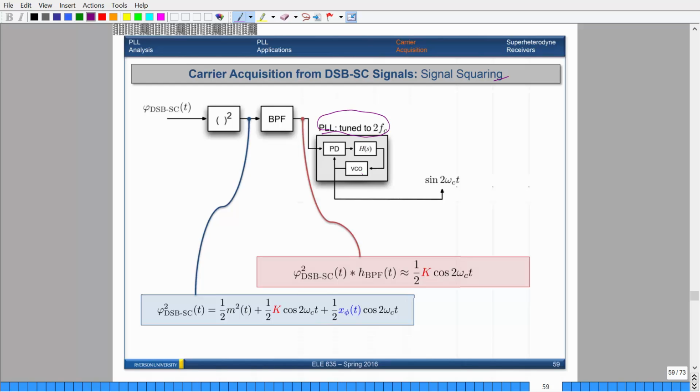So remember, this voltage controlled output, the f of 0, would basically be twice the carrier frequency, because that's what we're trying to extract, right? When you have your non-ideal bandpass filter, there might be some tolerances, some frequency changes, some errors. So you put an additional phase lock loop here to make sure that the output will be twice the carrier frequency.